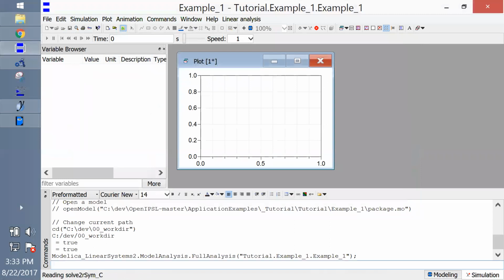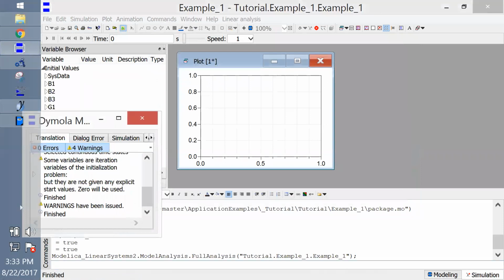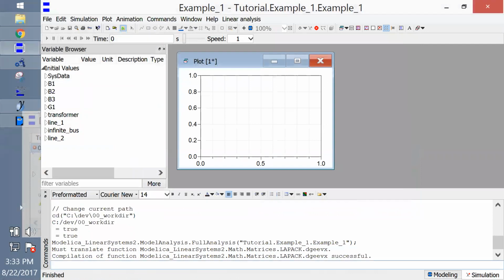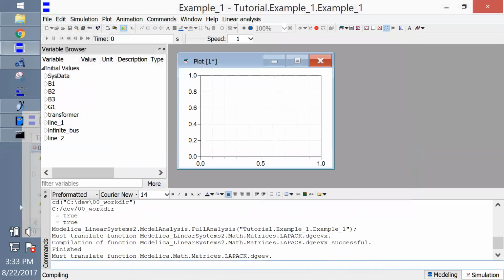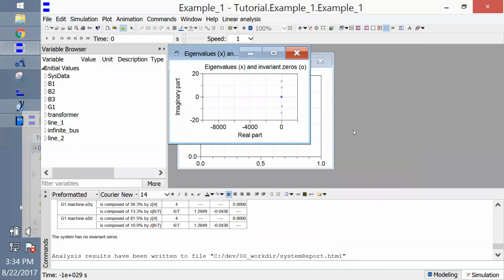And also at the beginning of the presentation, the Kundur example, it was unstable. Yeah. So is it like numerical instability? No, it's by design, right? Because we want to stabilize that system. So you just need to reduce the gains of the AVRs. It's designed like that. That's the idea. I mean, I don't want you to get a stable example. What's the point of dynamics if you get a stable example?